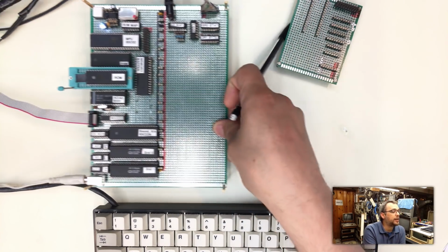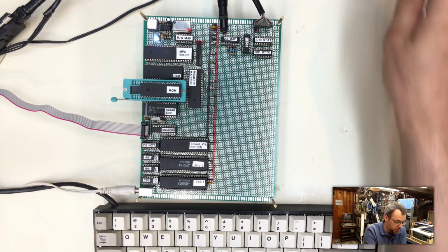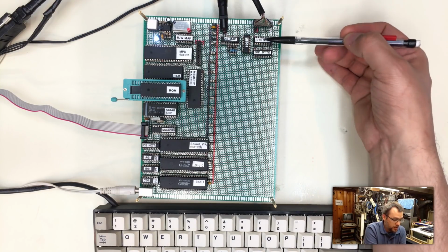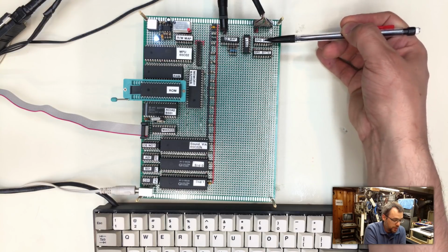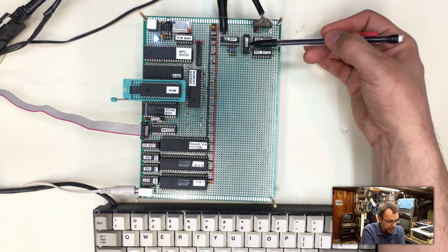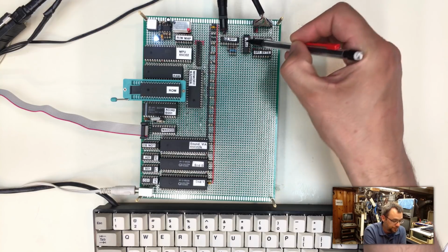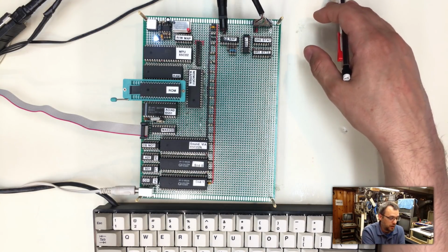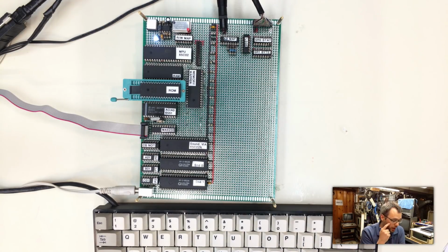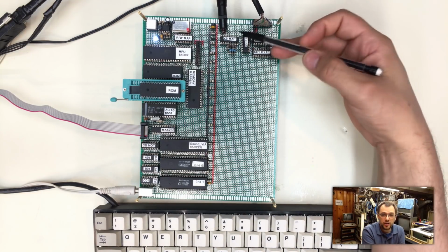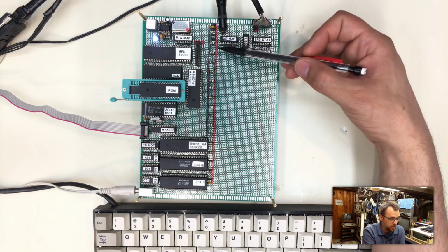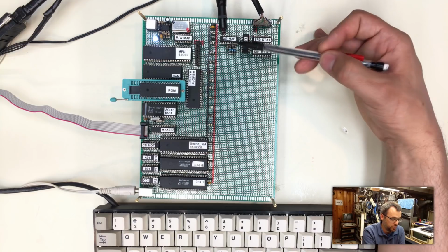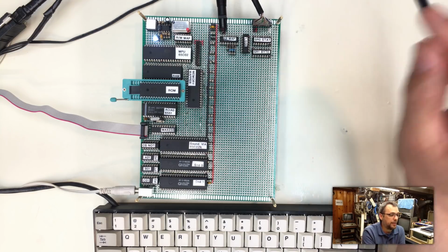this stuff right here on the board. So let's take a look at all of this real quick. Effectively, these three chips here, the status serial register, the byte serial register, and the LS08 chip that helps us determine how we're latching our data in on the register clock. This didn't change. None of this has changed. But this right here has replaced that ROM chip.